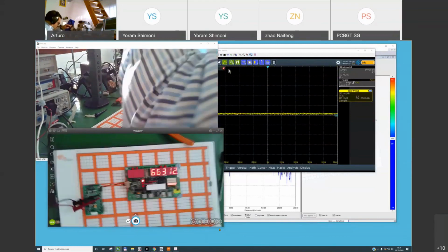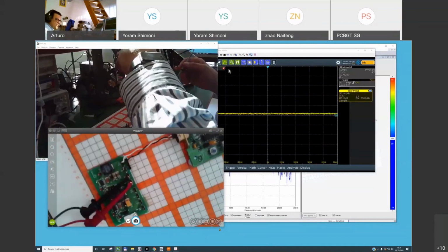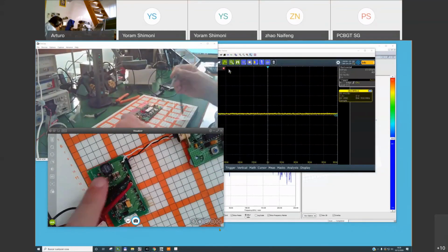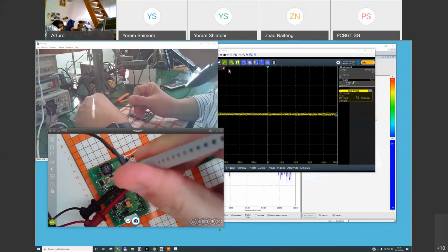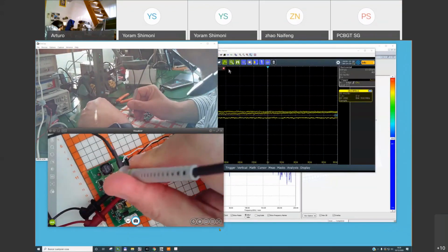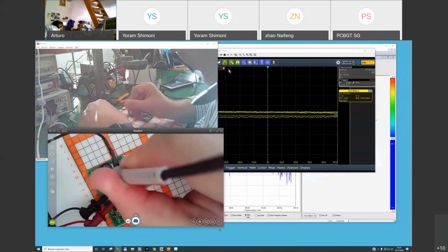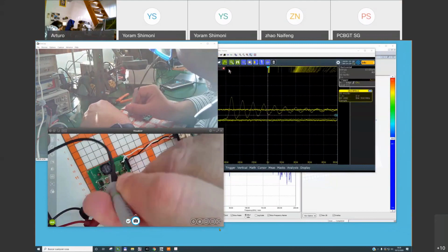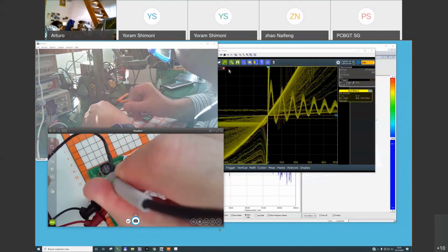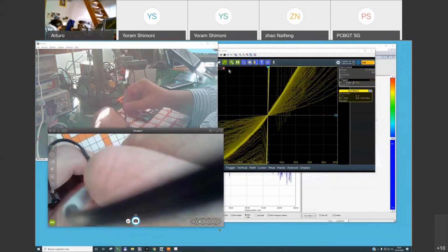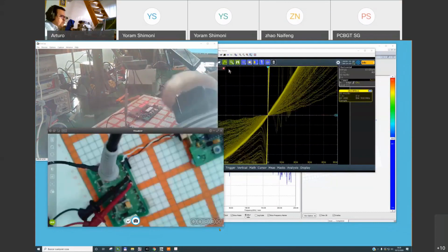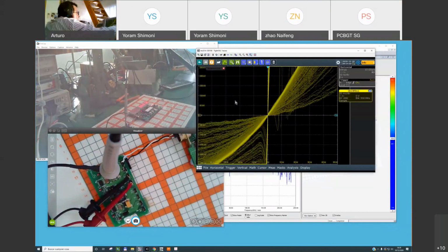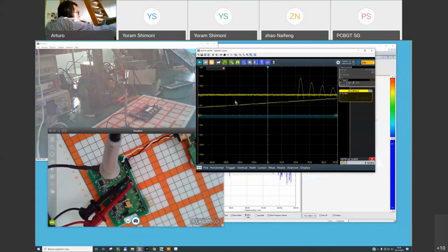And I usually work with this kind of sockets. So I have 2 sockets here, so I can connect my probe for measuring the switching activity of this device, without the pigtail. The pigtail can create ringing that is not in your circuit, it is created by your measurement. So you can see how is the switching activity of the transistor.